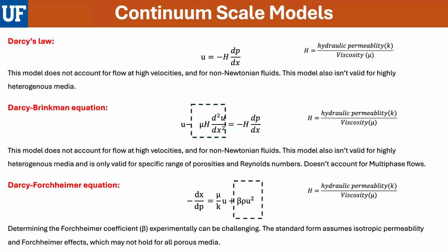Moving on to the continuum scale models, one of the most important equations that we use to model porous media is Darcy's equation, which provides the relationship between fluid velocity and the pressure with inclusion of certain pore parameters such as hydraulic permeability. To incorporate viscous effects of fluid flow in porous media, an extension of Darcy's equation called the Darcy-Brinkman equation is used, with a viscous coupling term which incorporates the viscous effects of fluid flow into it.